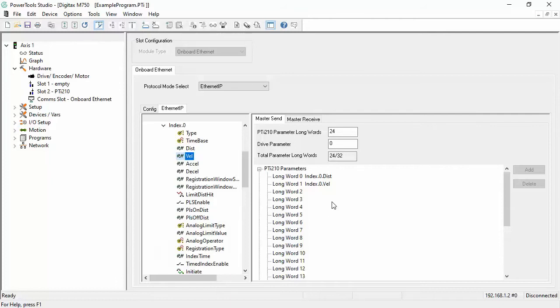Regardless of how you are setting up the PLC, whether it's using an EDS file and RSNetworx or manually, as I'm going to do, the PLC is not going to be able to distinguish what this data is. It's just numbers on the PLC side. You're going to need to record this so you know not only the total number, which I'll also touch on in a minute, but what the function of these words or registers are for. So those are both 32-bit parameters, so they consume both of these words.